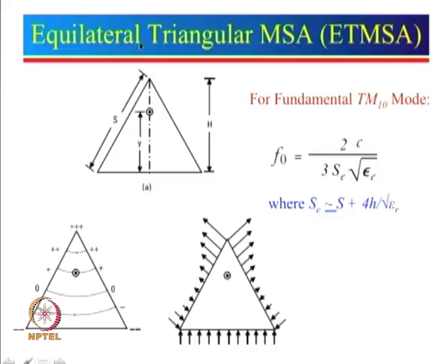And over here we have shown the feed point along the center. If you recall, every time we put the feed point on the central axis, for the rectangular patch and also for the circular, the reason is that if you put it in the center, with respect to this feed point it becomes a symmetrical antenna, and if it is symmetrical, then cross polar components get cancelled.